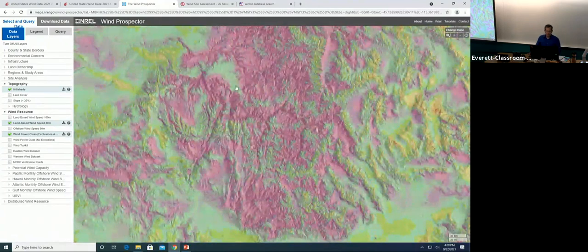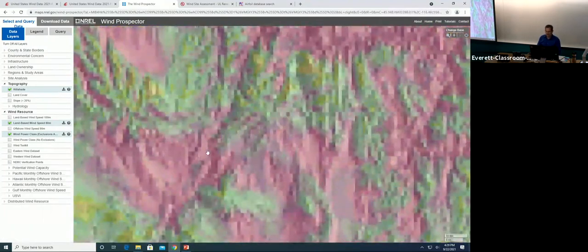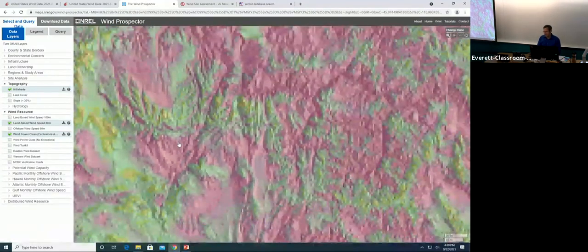Now, again, this is part of the NREL data set. That doesn't necessarily mean that somebody's actually put up a met mast and measured the wind at every single location. I think each pixel on here represents 1 square kilometer, okay? They haven't done that, right? They've used mathematical modeling and CFD, computational fluid dynamics, to model what the wind will be doing based on the nearest possible met mast.